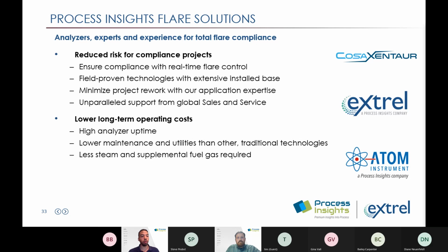And as you mentioned, there are many databases available with a lot of mass spectral information, those fingerprints. We have some of that in our software readily available. A lot of the more common hydrocarbons and other constituents are already programmed in our software, so that data is accessible by the user. But also the US government's NIST agency has a very large library of these mass spectra that many people have access to through Google.